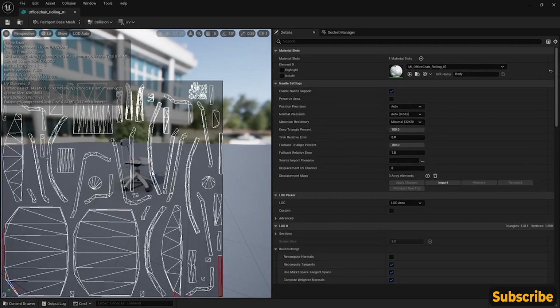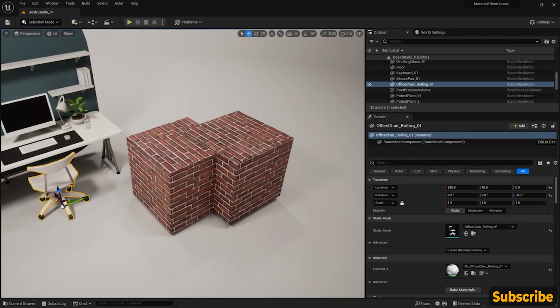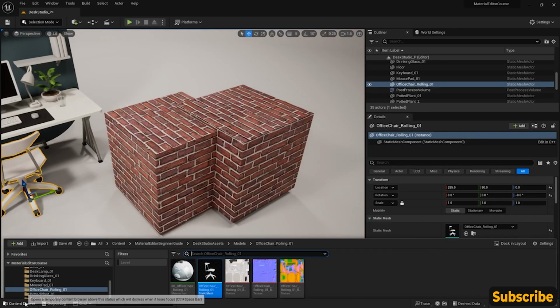So UV 0. So tangent space is where am I on this UV coordinate? And again, upper top corner here is 0, 0. Bottom corner here is 1, 1, because again, X and Y. So that position is being converted from a world position, changed into a position that Unreal can look at in this context, which is very useful for us when we're trying to work on materials.